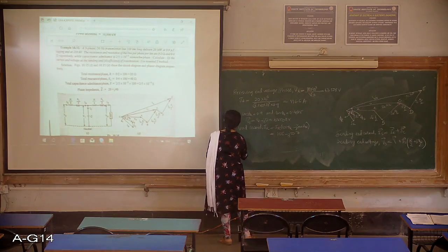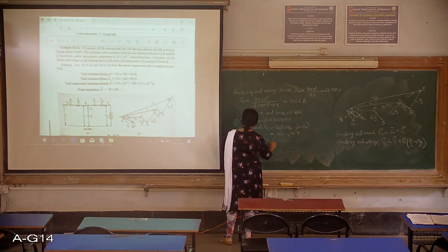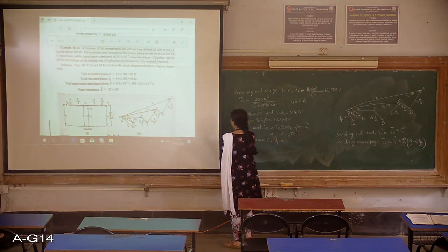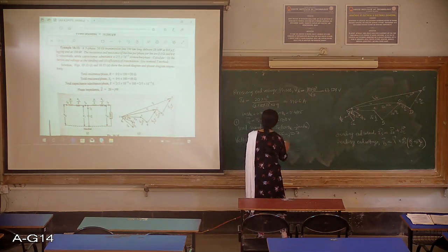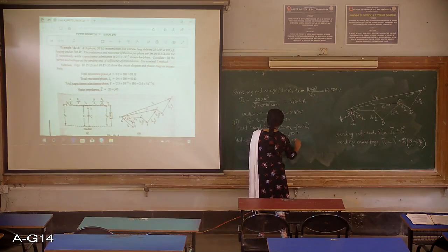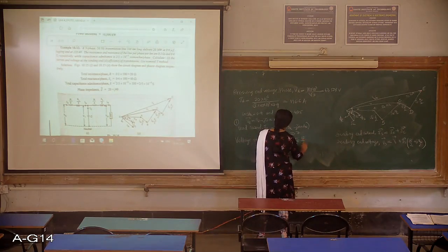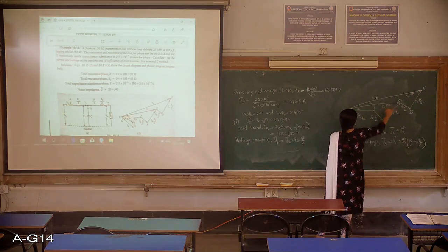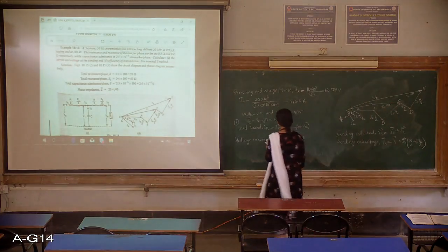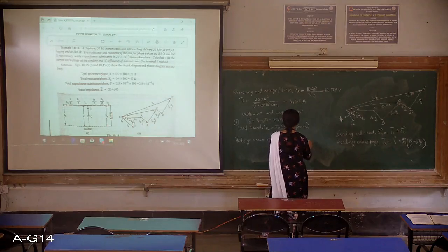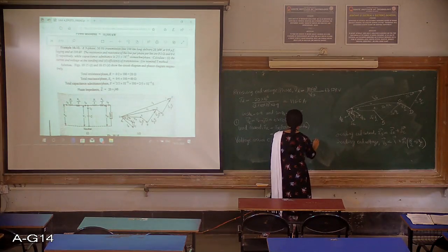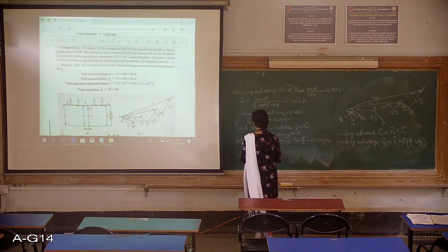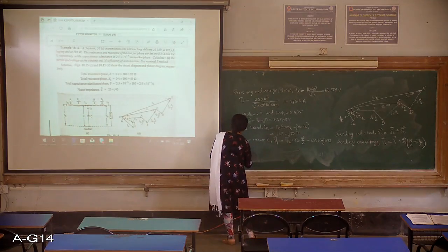Then the capacitor voltage, or voltage across C, which is V1. Refer to the phasor diagram. V1 is VR plus IR into Z by 2. You can see here also, V1 is VR plus IR into Z by 2. So this value turns out to be 65,572 plus J1593.